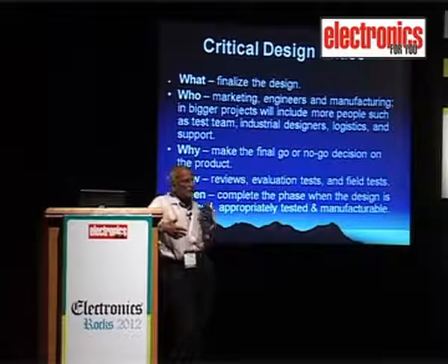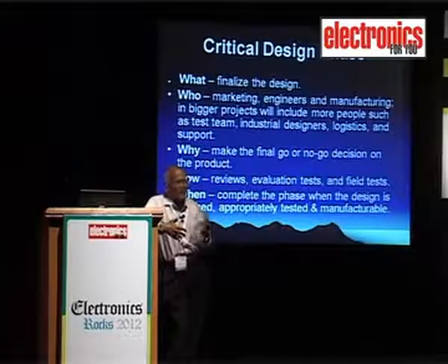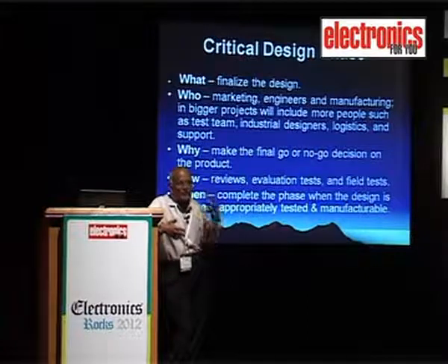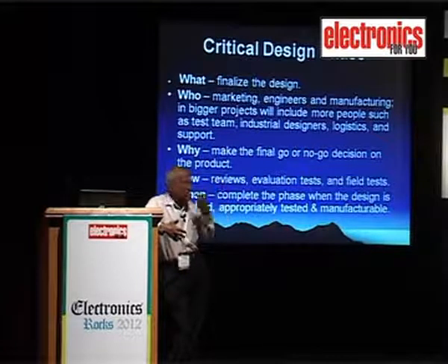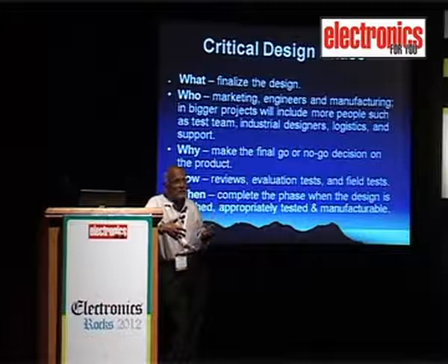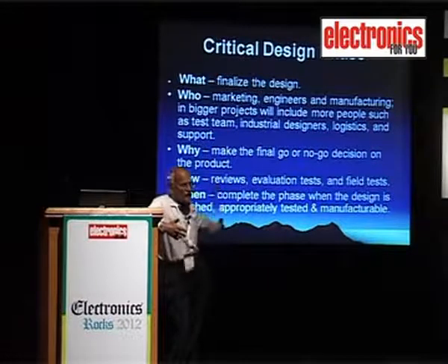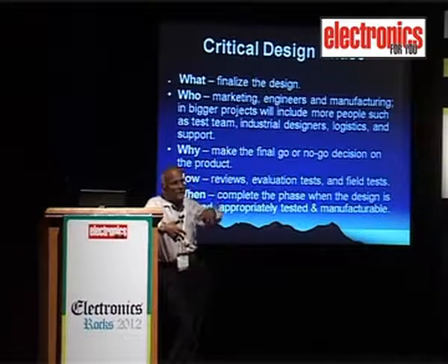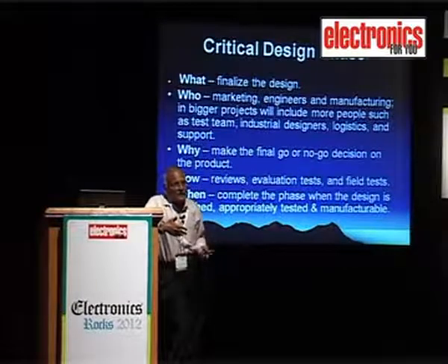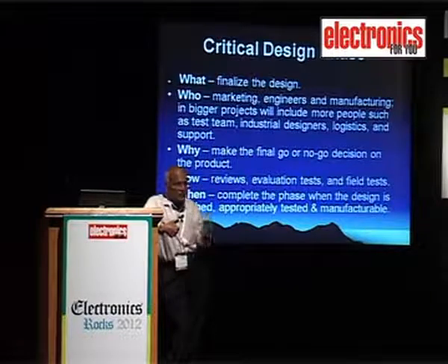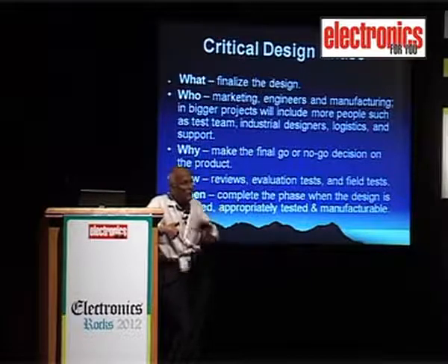3 years ago, quite a lot of people in Bombay lost their television sets and their laptops connected to the mains because of a very big lightning strike in Mumbai city. So today, like what you were talking about, the ESD and the lightning, the products can get damaged. Earlier the specifications were 2 kV, now the specifications have gone up to 4 kV for household appliances.